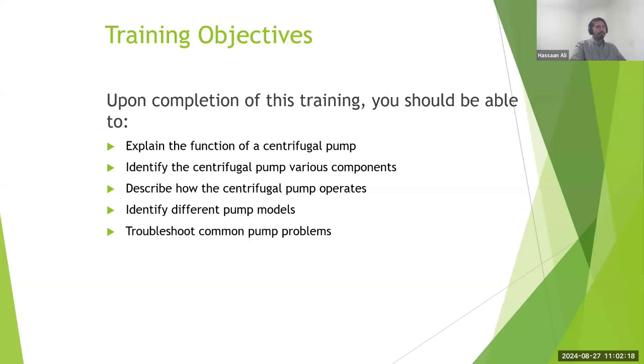One of the ways you can prevent cavitation in the centrifugal pump is making sure that it is primed all the time. That means it's not running dry or running on partial fluid conditions. That means there is fluid coming, but it's very little compared to the rest; if the fluid is not there, it will be filled by air. So make sure that air is not there, because that can also result in some of the cavitation issues.